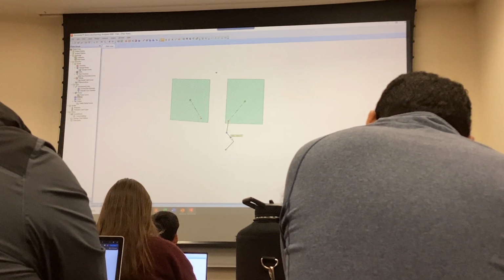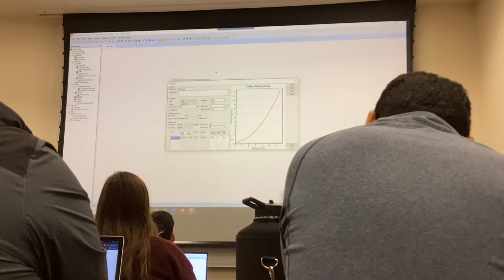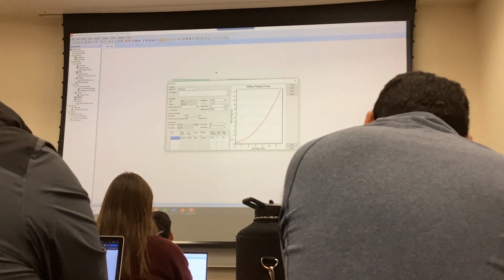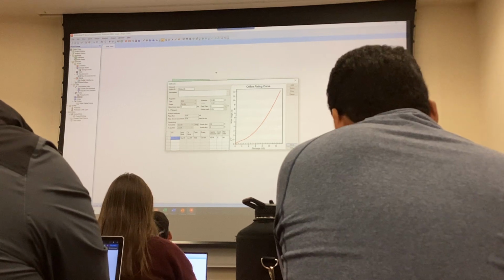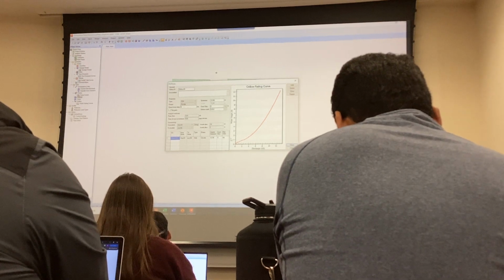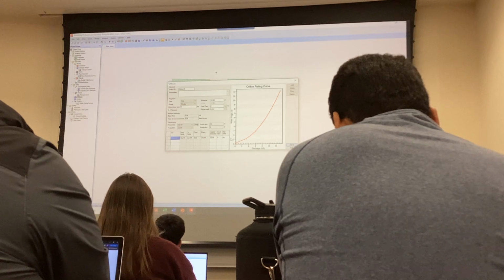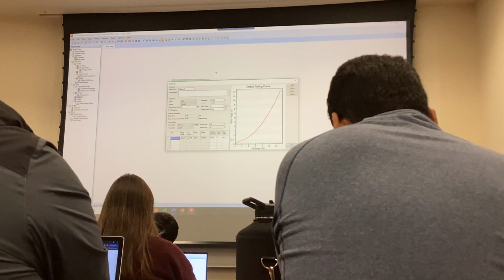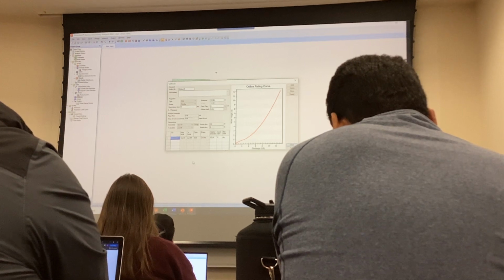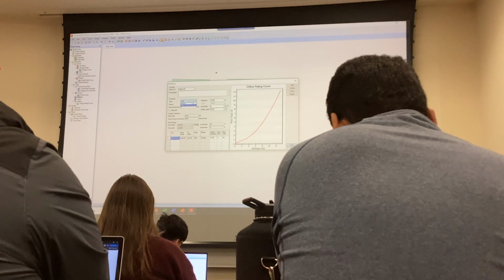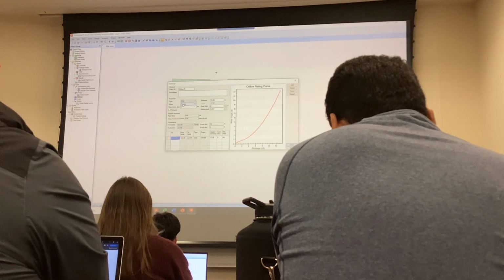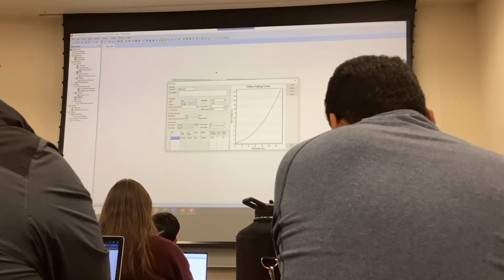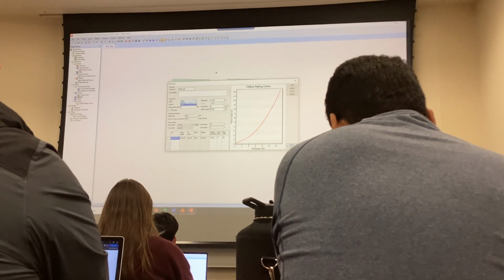So click on that orifice, and now you have the option to put in the size, where the elevation of your orifice ought to be, right? And then how many of these orifices you're going to use at the same tier, and so on and so forth. Okay? So let's say I want to put a circular orifice. Okay? Circular, you select circular, and then the pipe is on the side of your detention basin box. Okay? You can put it on the bottom.